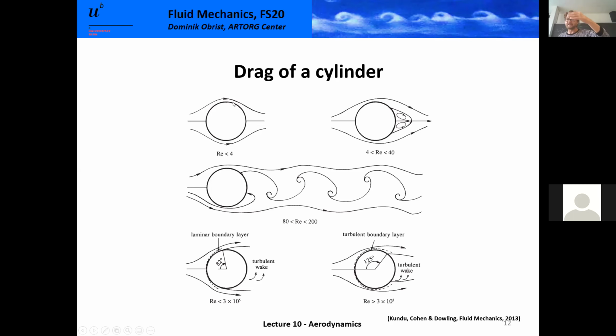At the same time, due to this friction, the flow loses energy, in the sense that it loses pressure. So just due to this friction, the pressure here will be lower than the pressure on the upstream side. So we also have a contribution of the pressure drag. So this is the Stokes flow configuration. This is a cylinder, but for the case of the sphere, we noted that about 1/3 comes from the pressure drag, about 2/3 from the friction.